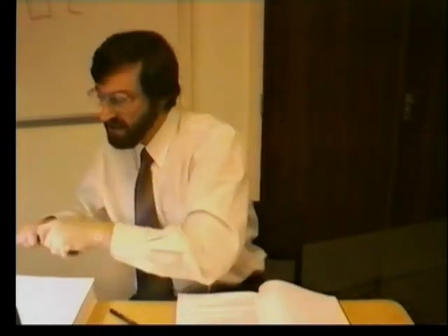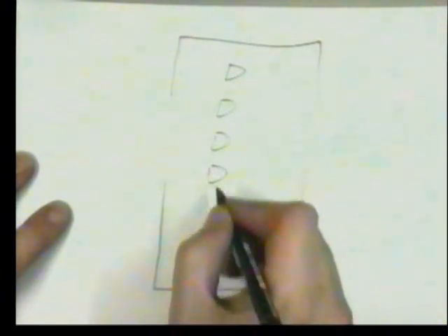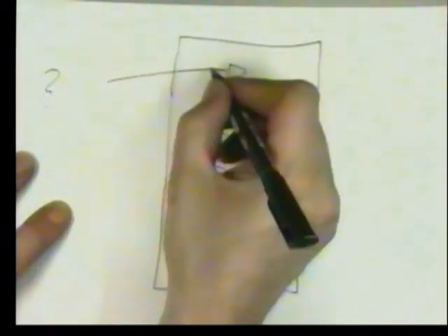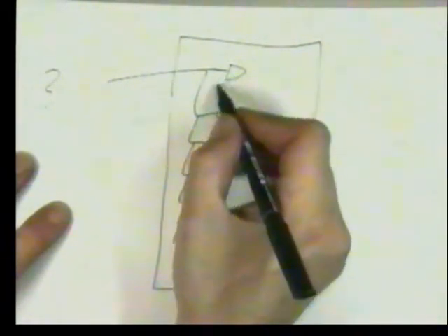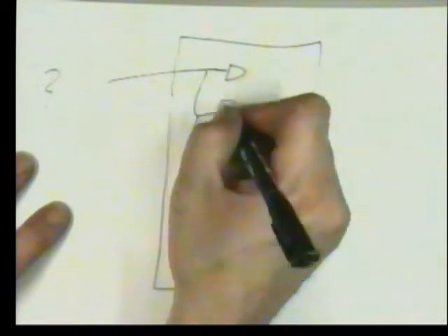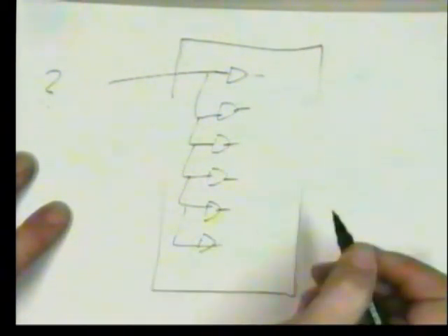And instead, you have a circuit where instead of one comparator, you have hundreds of comparators, literally. And you bring in our unknown voltage, goes to every one simultaneously. And instead of varying the trial voltage on them, these are fixed. Every one of these is fixed, and there is a comparator for every possible solution.